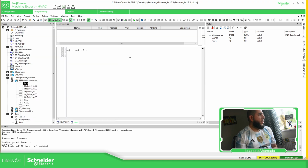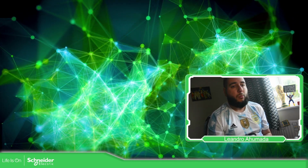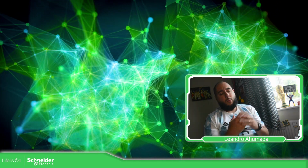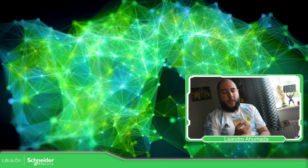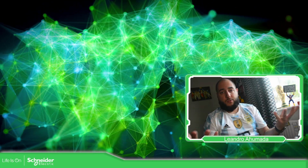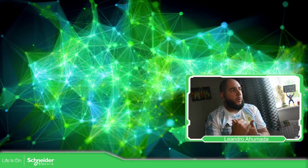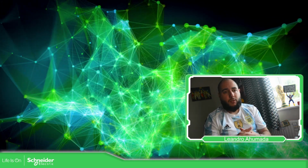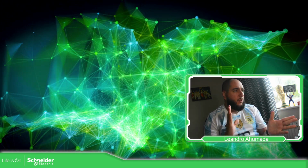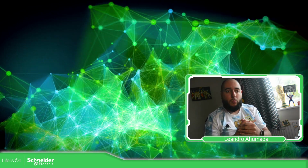So this is how we can work with the simulation, how we can simulate a PLC on our laptop, and how we can work with the code and see what's really happening without having the real PLC. Of course, if you want to test communication things, then you must have a PLC to test it. So this is it for the simulation mode, the M172, and it can also be used for the M171.